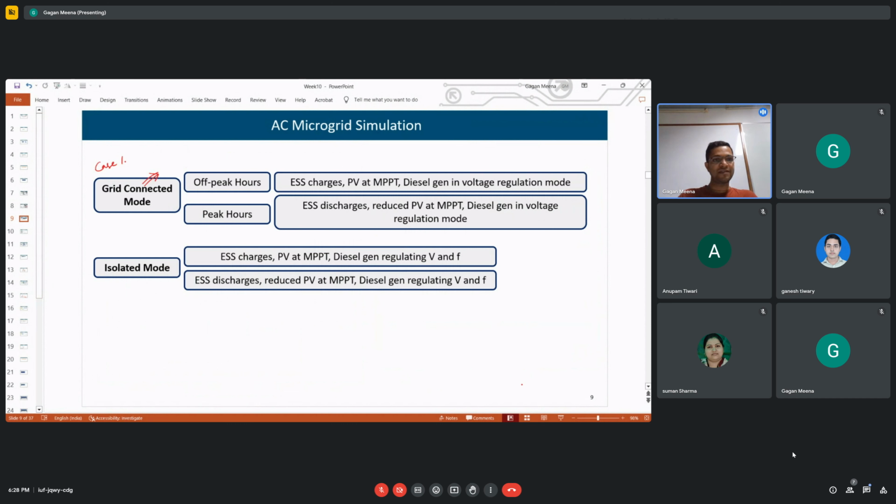We have divided the load. We have basement, ground, and first floor, so we have divided the loads. Even on each floor, the loads have been distributed in these three phases. Sometimes it happens that one of the phases is not available from the supply substation. Then in one room the equipment is working, but in the kitchen the refrigerator is not working. It happens because the load is distributed in all three phases. And it is not always that the load on all three phases is the same. So in that case there will be unbalance.